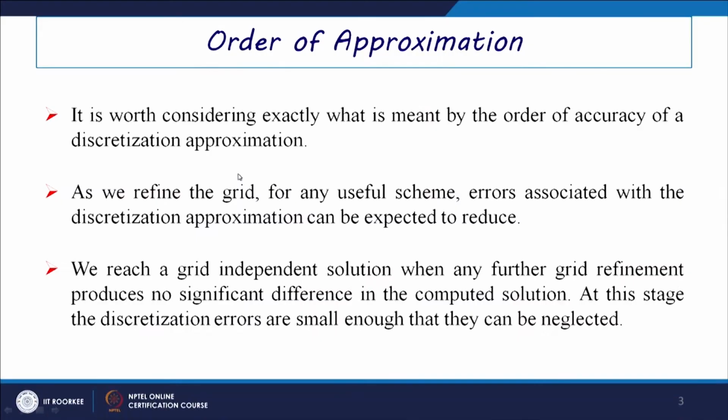So, when we reach this grid independent solution, it means that for further grid refinement, we will not find any significant difference in the solution process, and at this stage the discretization errors are small enough that they can be neglected.